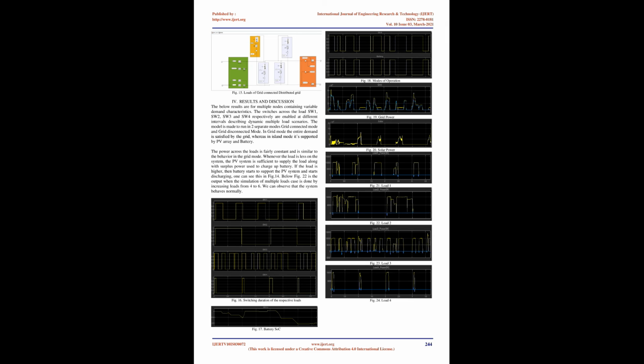Battery module. The battery module implements a generic model that represents the most widely used type of rechargeable batteries. This Fig 5 shows the equivalent circuit model which the block models. In order to calculate the voltage, the block implements these equations. The state of charge, SOC, of a battery is a typical measure of the battery's charge, expressed as a percent of the full charge. The depth of discharge, DOD, is the numerical complement of the SOC, such that DOD equals 100% minus SOC.